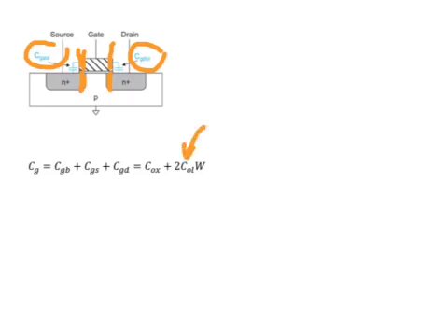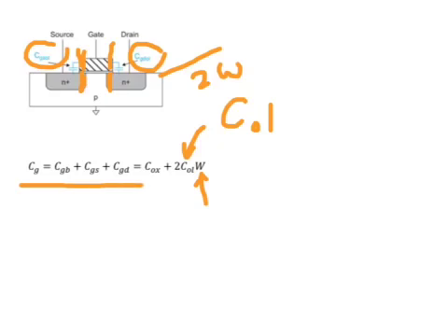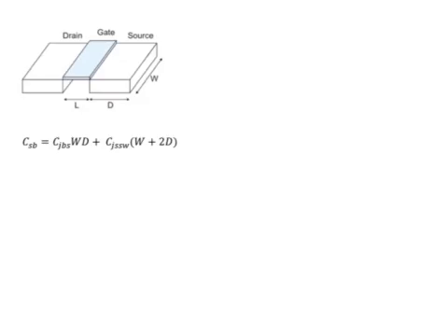As you can see here, it's parameterized by a normalized parameter, the overlap capacitance, and then multiplied by the width of the transistor. So transistors with twice the width will have twice the overlap capacitance. So all these together collectively form the gate capacitance. So the gate to source capacitance also comprises a certain contribution from the overlap capacitance.